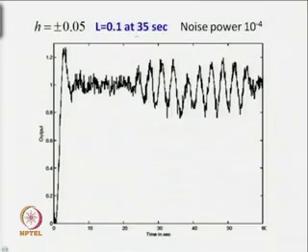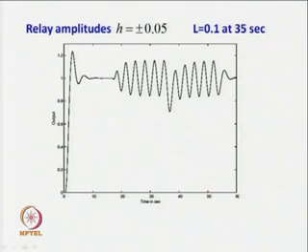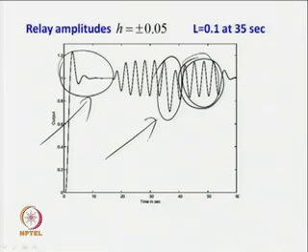The main reason for that is, as I have said earlier, we have to look for the signal that we get after the static load disturbance. We have to collect information from the last few cycles of the output signal, not from the period where you have normal operation, because once you have the static load disturbance, the output gets distorted.